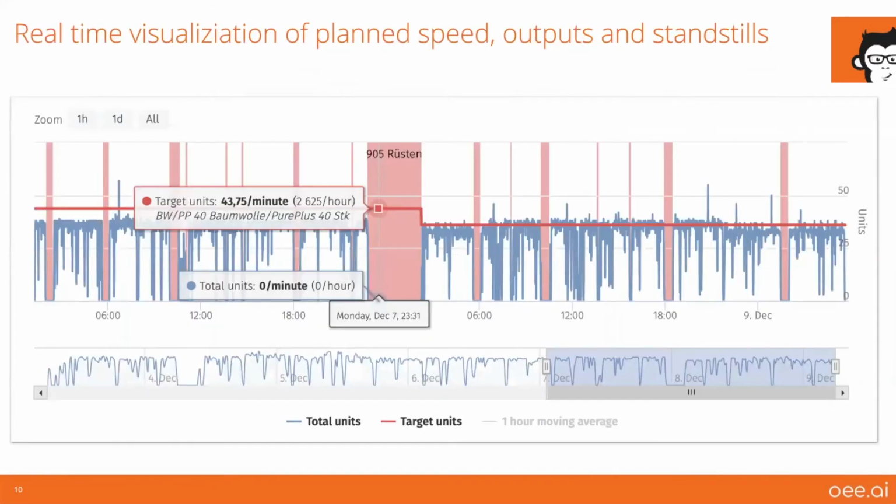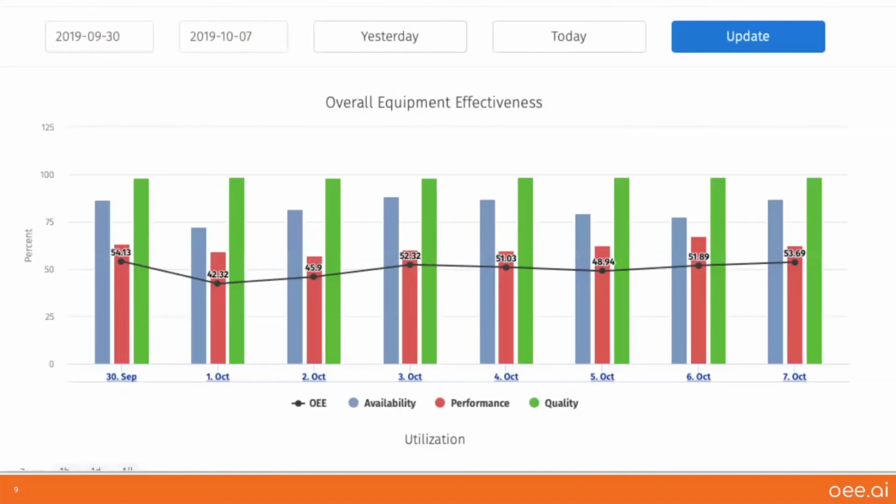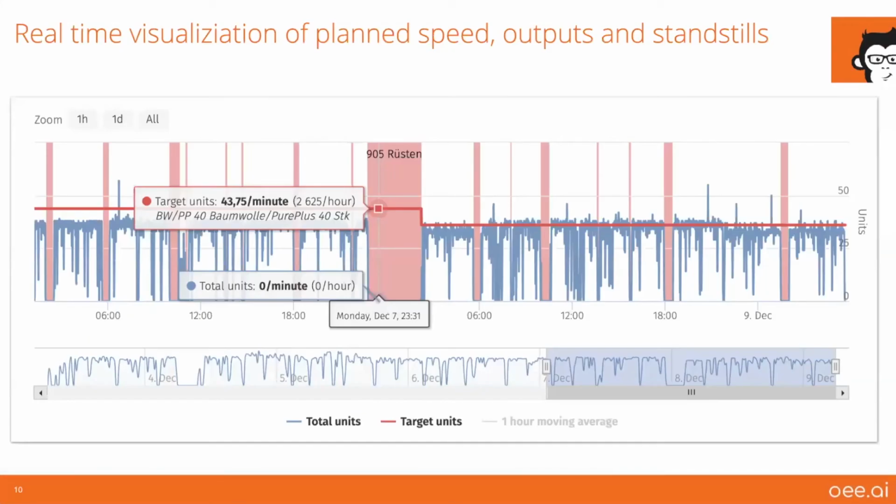When I go back a little bit to the OEE, you can see that the performance grade, or performance factor here, is by far lower than the availability factor. And the reason for this is that it's much less transparent. If the machine is running, like on the left side, with a small gap to the desired time, there is a loss reason. That is a loss. But the loss at that point is a performance loss.